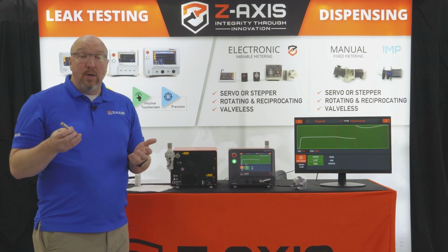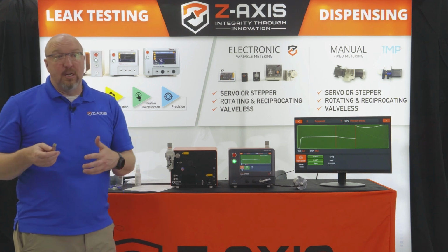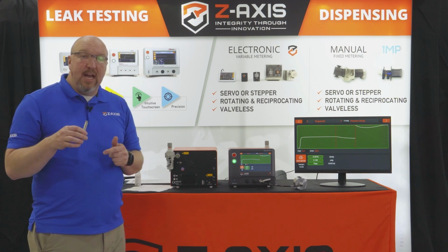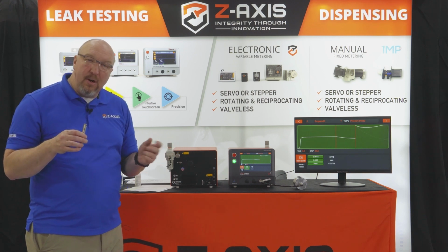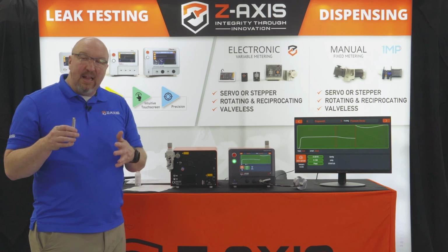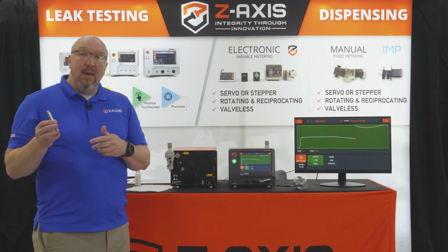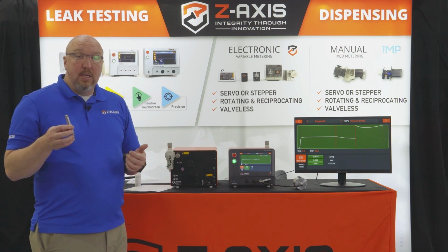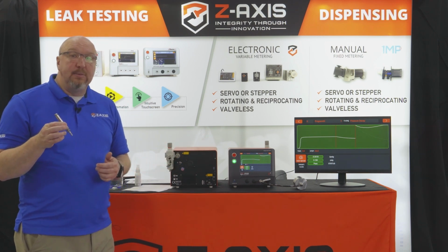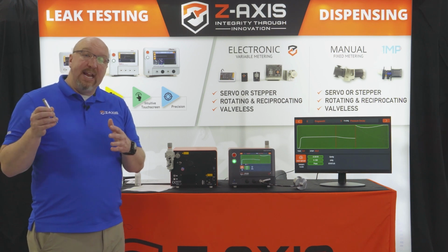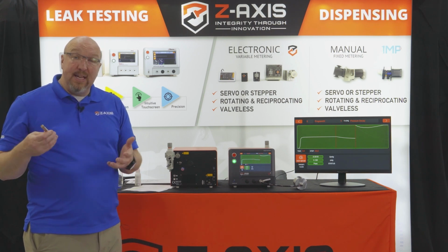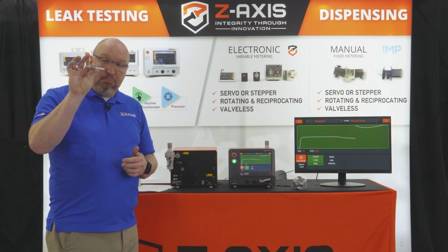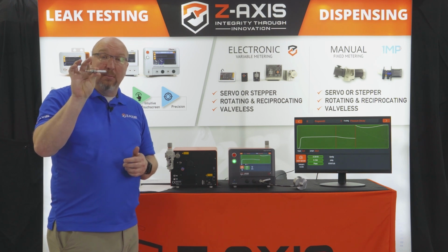So something that needs to be watertight, based on our other customers and our history and our experience, we understand that for something to be watertight, air can actually leak out of it. And there's a certain amount of air that can leak that will tell us if it's less than that amount of air, then we know that water won't leak out. If it's greater than that air leak, water will leak out. So for example, 2 cc's per minute seems to be a spot where we can get air to leak out of the system, but when we apply the same amount of water, water won't come out of the system. So we can make that into a calibrated leak with a traceable calibration on it.